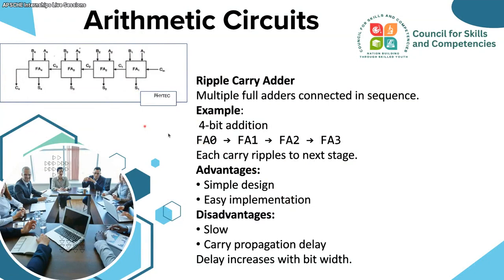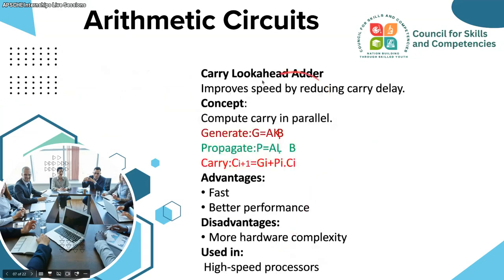But the disadvantage is it is too slow, because of carry propagation delay, since the carry has to go here, here, here, here. So the delay increases with bit width. Suppose you are using 8-bit addition, then again you need 8 full adders, and it keeps going on like this. So for that, they introduced something called carry look ahead.